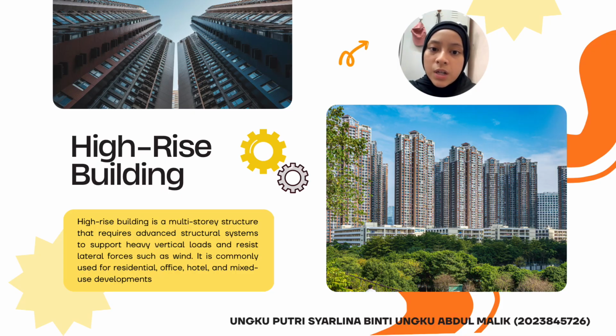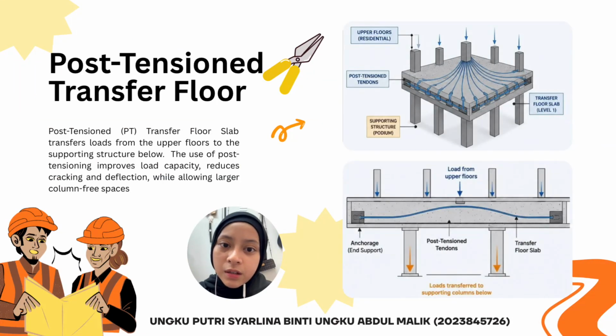So for our case study, we are focusing on the high-rise building that uses a post-tension transfer floor system. Let's see what is the meaning of post-tension transfer floor. Let me briefly explain. In a high-rise building, the upper floors often have a different column layout from the lower floors. So a transfer floor is used to transfer the load safely to the supporting structure below.